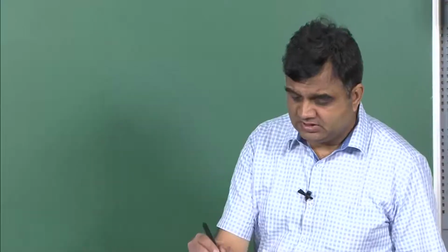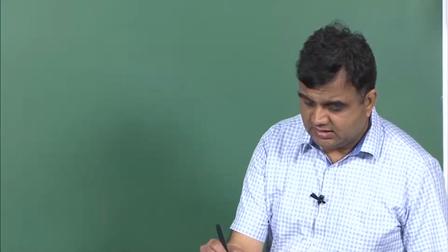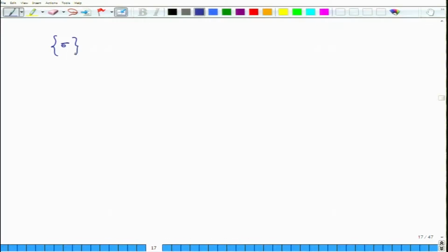So, what we have shown is that we can now calculate sigma x, when you measure stress with respect to x and y plane. That is equal to a matrix Q bar times a strain vector measured with respect to x axis, and we know how to calculate all the elements of the Q bar matrix.